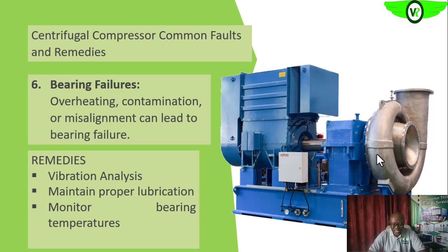so that it will reduce bearing failure. Then the temperature too of the bearing: when the bearing is malfunctioning, you see that the bearing temperature will be increasing. If the grease is not enough, the bearing temperature will also increase. If we have excessive grease, that can also increase the bearing temperature. So the bearing temperature is an important parameter in the operation of the compressor that we should always be monitoring, so that if it is deviating from what is normal, we know that something is developing.